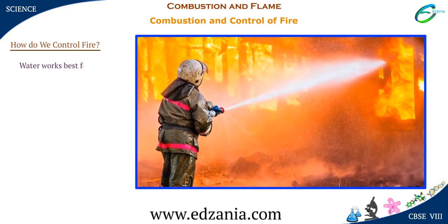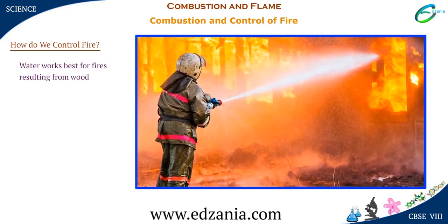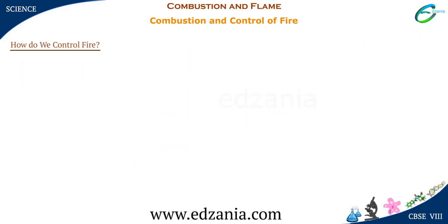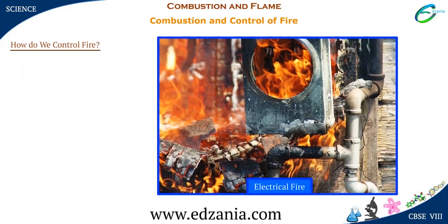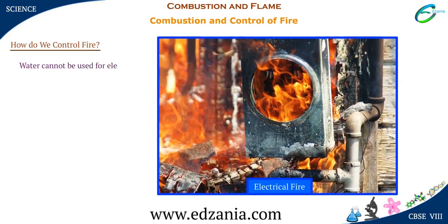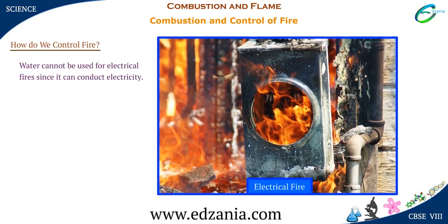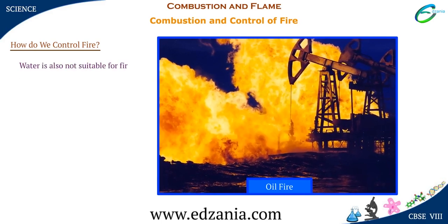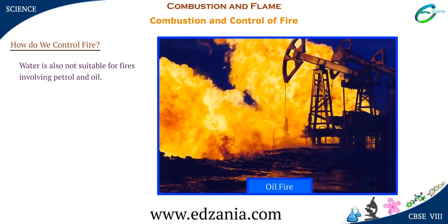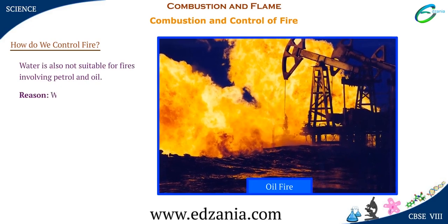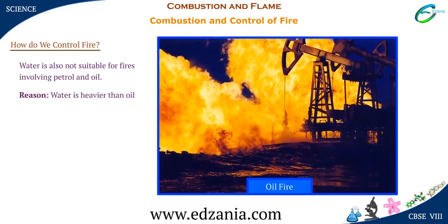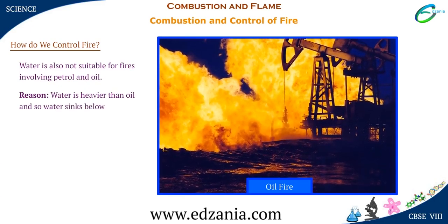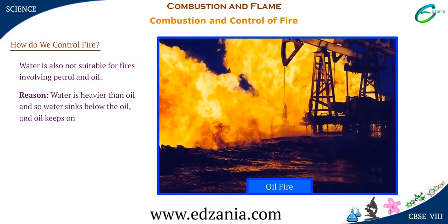But water works best for fires resulting from wood and paper. In case of electrical fires, water cannot be used since it can conduct electricity. Water is also not suitable for fires involving petrol and oil. This is because water is heavier than oil, and so water sinks below the oil and oil keeps on burning